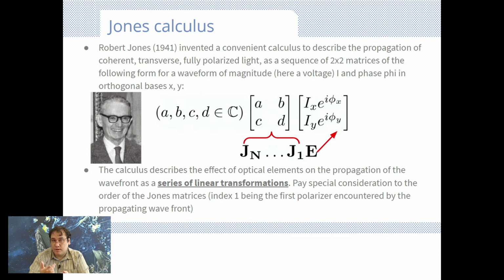So let's say nominally aligned vertical and horizontal bases, and a phase angle that describes the temporal variation as the signal propagates through free space. That is the signal that's unaffected by any calibration errors that is induced by either the environment or the system.